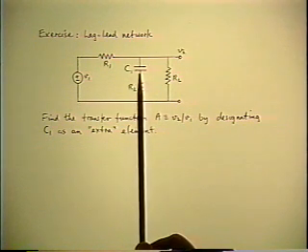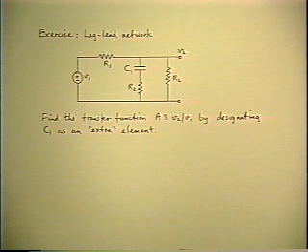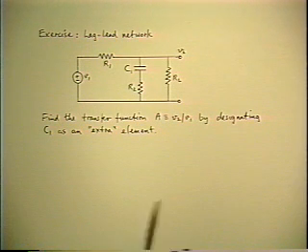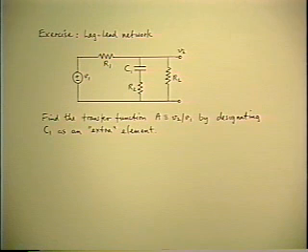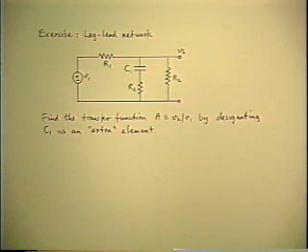Throw it away, and then what's left is a purely resistive network, and it becomes almost ridiculously easy to solve for the reference gain and the two driving point resistances. All you have to do is put the capacitor back into the correction factor, and you've got the answer. Well, this is so easy that I won't even do the example. You try it right away.